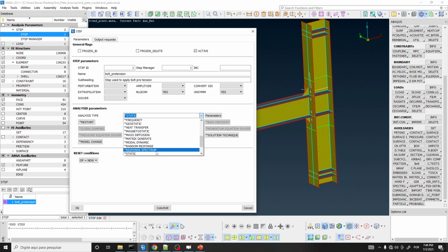But here we have other kinds of solvers as well. You see, I have the buckle that performs linear buckling analysis. Maybe we can perform an exercise like this. In the course, we have performed exercises using the linear buckling solver, but we can perform some more complex analysis, such as one I recently performed of a very large water tank, where I needed to calculate the buckling load using the linear buckling solver, and then I needed to also calculate buckling using a nonlinear solver by using the results of this one. It's a pretty interesting procedure. If you'd like to, I can show it to you.